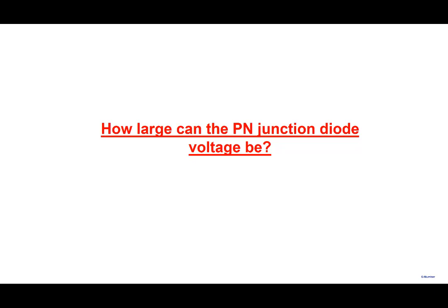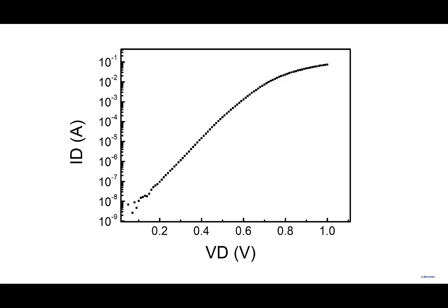Let me show you again. This is the measured diode characteristics, the same 1N4007. A nice exponential, and then as you go to higher and higher biases, the current starts to saturate here. The current is nicely exponential up to a point, and as you increase, note that it begins to depart, in this case even at 0.7. 0.7 is over here, and it is no longer a pure exponential.